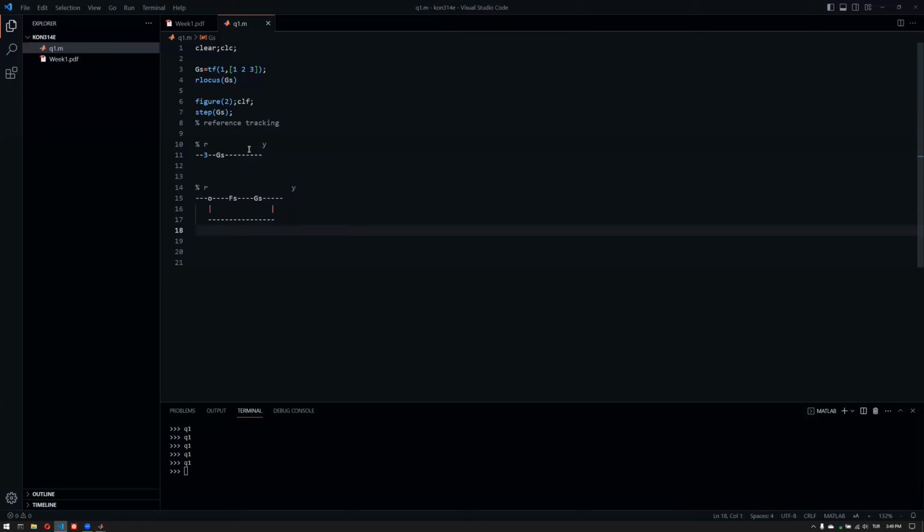So in this case, you end up in a certain feedback loop because you're measuring the output Y, and you're looking at the difference between the reference input that you're applying to the system and the system's output. You then have an idea, for the car or vehicle example, if you're slower than you should be, or if you're faster than you should be, if you're going downhill or uphill, then you can evaluate that because you took measurement. And then the controller acts upon that measurement and applies a certain input to your system. So closed loop, therefore, this feedback loop here, is a better strategy.